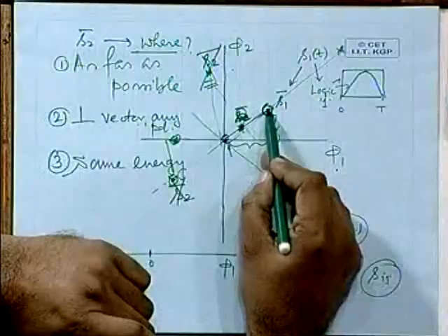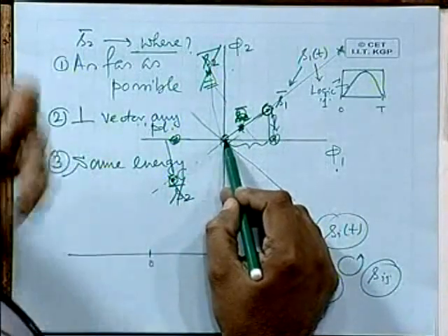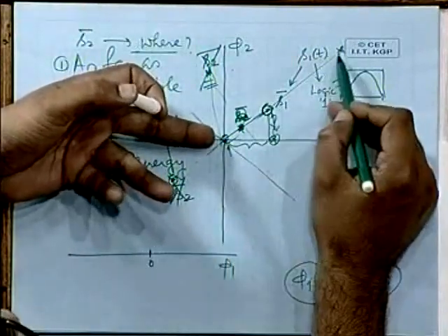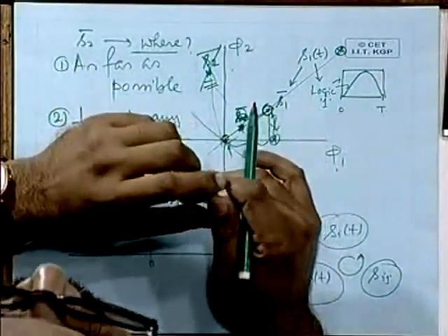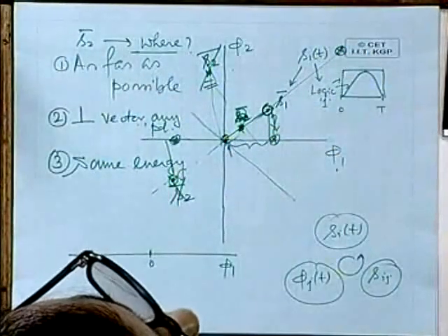So that depends on the choice of origin. This origin you have to choose at the beginning, you can place it anywhere, and then with reference to that the axes are placed. Once those are placed, compared to the earlier situation of S1 being placed here and S2 being placed at the origin, now if I change my style and say that let S2 be here and S1 let it be here, I have drawn it further away. So, what I have essentially done is that I have increased the power associated with S1, or increased the energy fundamentally, and then considering that both of them are equally probable with probability 0.5, I can say the average transmission power has increased, isn't it? So, the points should be so designed that the average transmission power is not unduly increased.